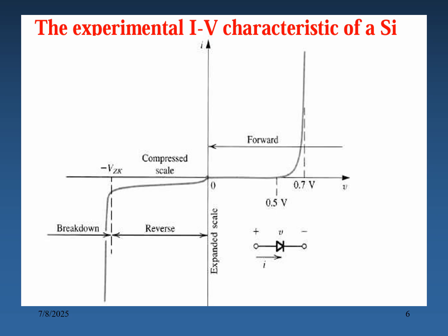For a silicon PN junction diode, the cut-in voltage is 0.7. That means the barrier potential of the depletion layer offers a potential up to 0.7 volts. That means up to an applied voltage of 0.7 there is no current.